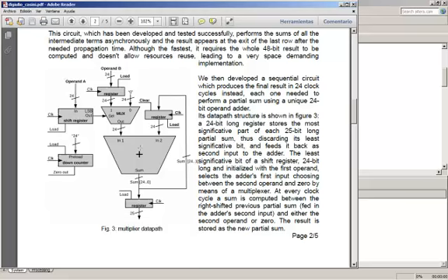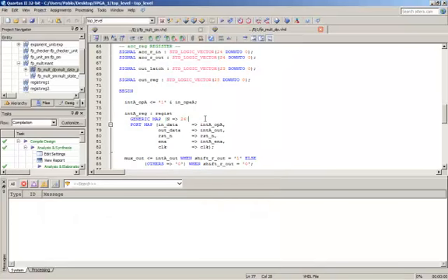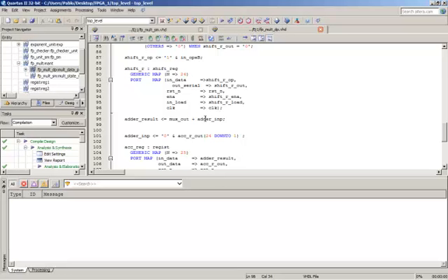The shifting of the data is performed through this path. Once the data goes out from the register, we take part of this register and concatenate it with 0, performing the shift. We execute this loop as many times as the counter says. In our case, the multiplication is 24 bits times 24 bits, so the preload down counter counts from 24 till 0. Once we perform the multiplication and addition, we stop and send the signal that says all the multiplication was performed.